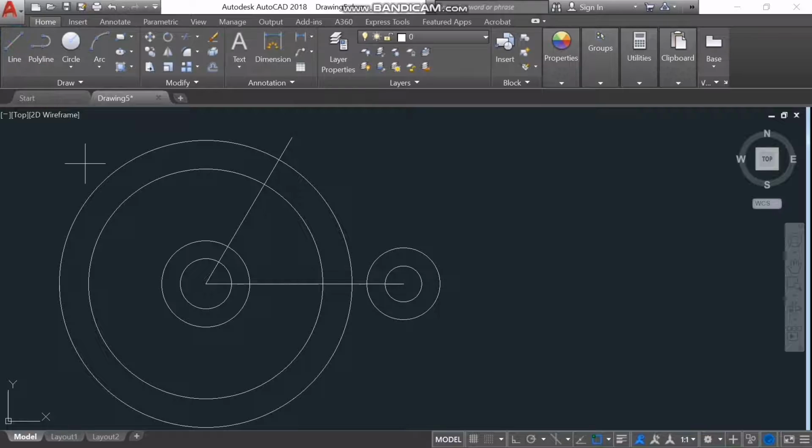So we activate our line command, press this side, and now we're going to take the counterclockwise direction. If you monitor my cursor, you can see where AutoCAD is reading the angle from. I want to read it from counterclockwise, so I'll just bring it up here, specify any length, press tab to activate my angle box, and then input 195 degrees and press enter. Press escape to cancel the command.